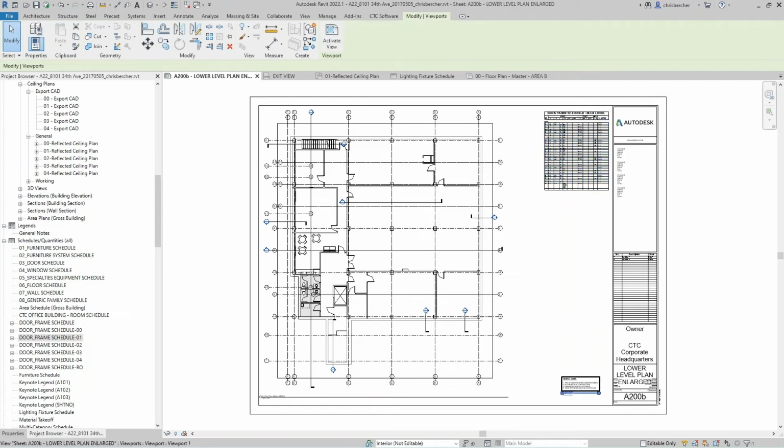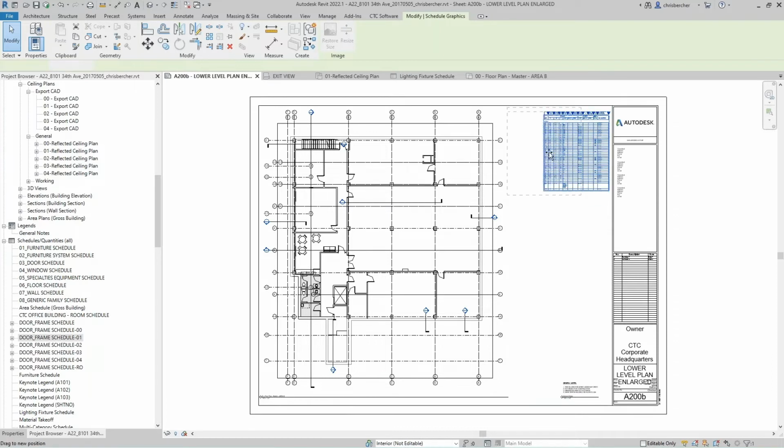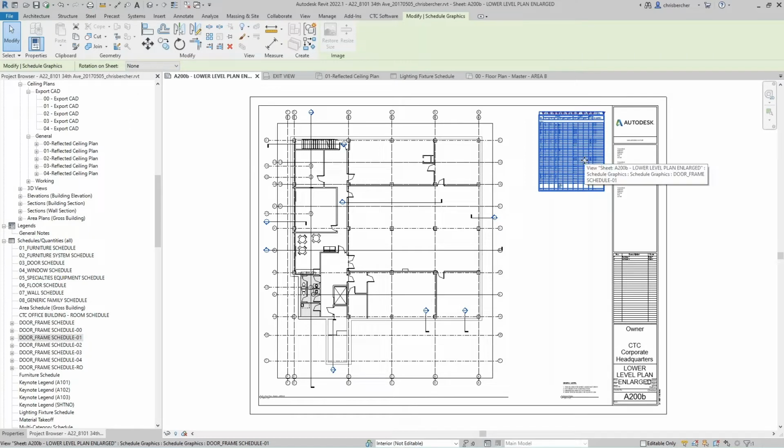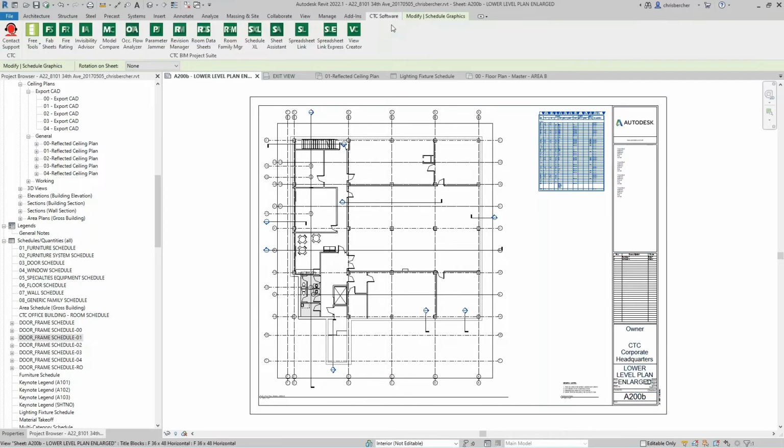Right? Now, we have another free tool called View Aligner that can sort of assist with this. Revit has its built-in alignment views, but that only works on similar view types. So model views can do its thing. Schedules can line up with each other, but you can't line the two of them up together. So View Aligner, which is our free tool here, does help you with that.